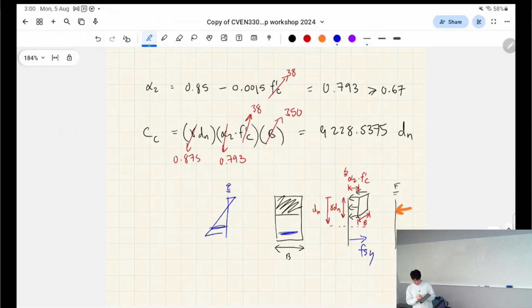So when we're designing doubly reinforced concrete, we generally consider the tensile bars as yielded, and the compressive bars as not yielded, because the compressive bars aren't pulled very much. Oftentimes, the compressive bars' only role is to shift the neutral axis up so that the tensile bars can do more and take on more force, basically, right?